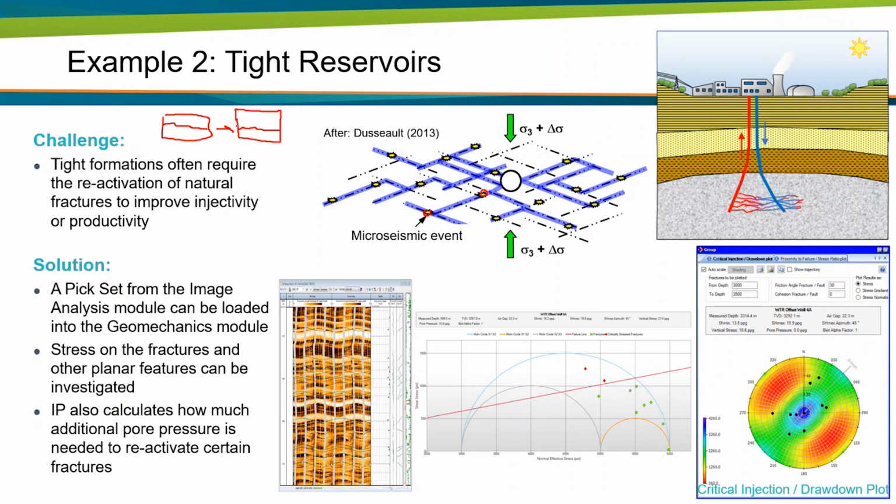And because the fracture surface is not completely smooth, but it has a dilatancy angle, you actually create a flow path through the fracture, and that's how you increase the permeability. So this is what you want to do in tight reservoirs. This is also what you want to do, for instance, in geothermal projects when you want to circulate through what